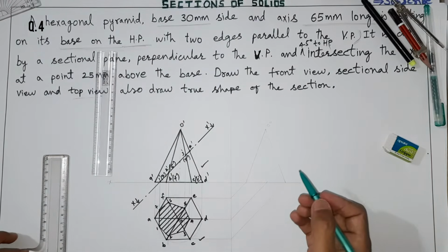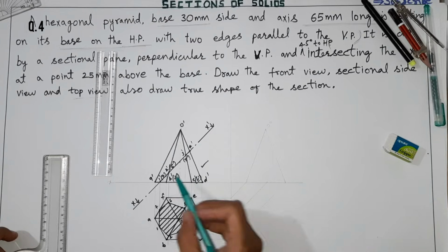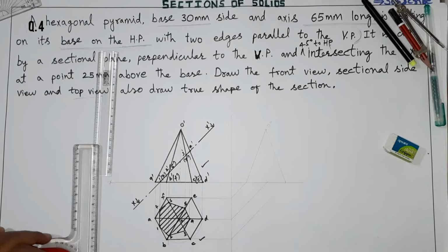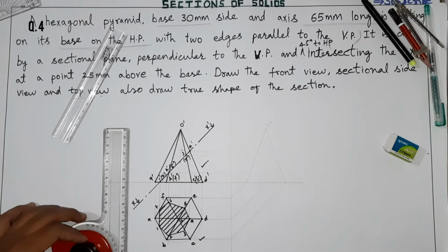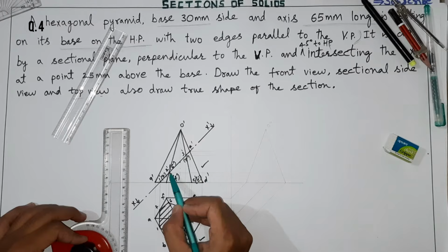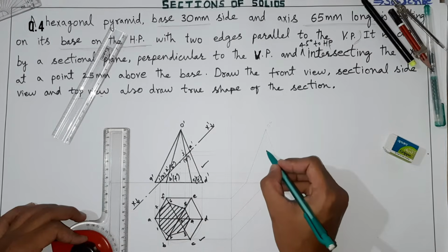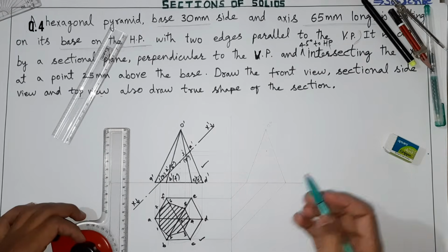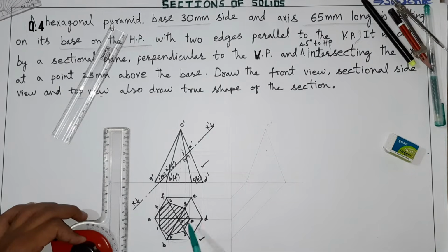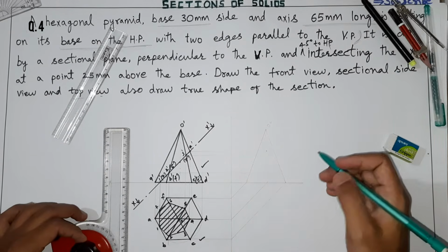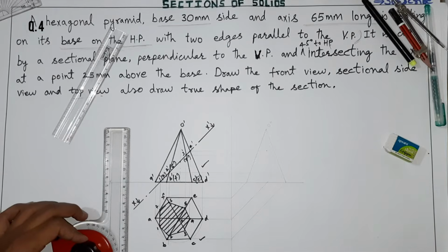Now after cutting, how it looks, we have to draw that also. From here you need to take points. Okay, let us see one by one. What I have taken is the fourth point, third point, second point, 3 points I have projected here. So this is the highest point in our side view. Now one more thing you have to do, you have to take 1 2 3, all this top view section points here, and then from here 45 degree you have to tilt it. So quickly I will do that.